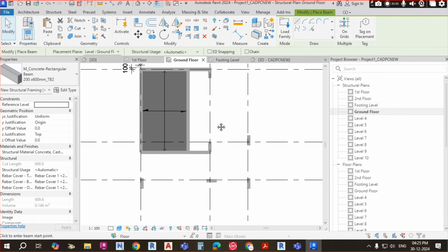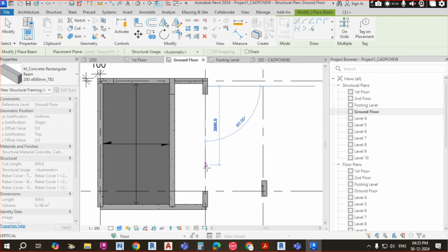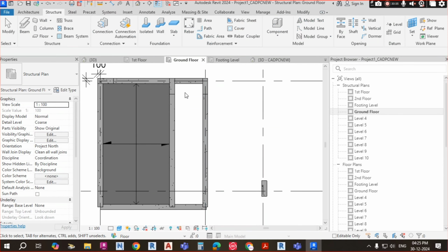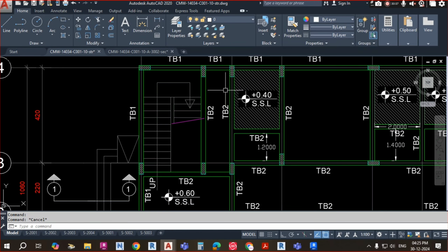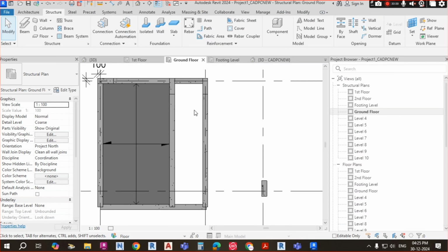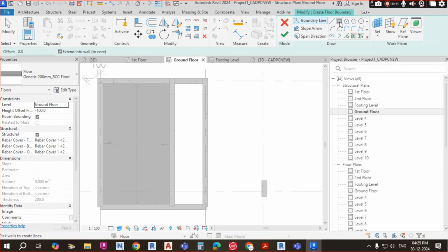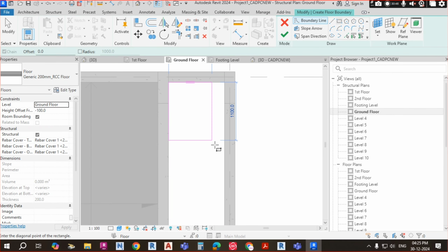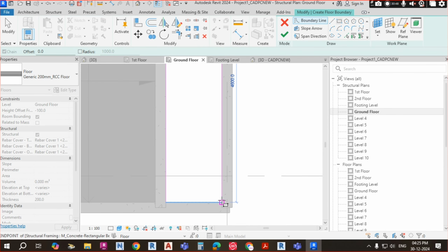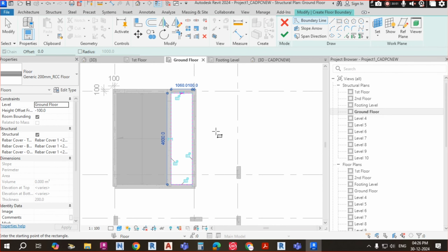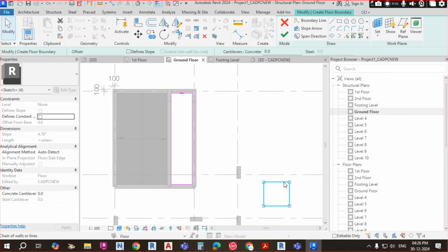So now I have one more floor I am making here, end to end. Now here also one more floor, this floor. Okay, the same process again: check structure floor, sketch it again from beam end to beam end, because each and every floor you have to sketch separately. Don't go like that, because after sketching one floor complete, I will sketch one more floor like that.